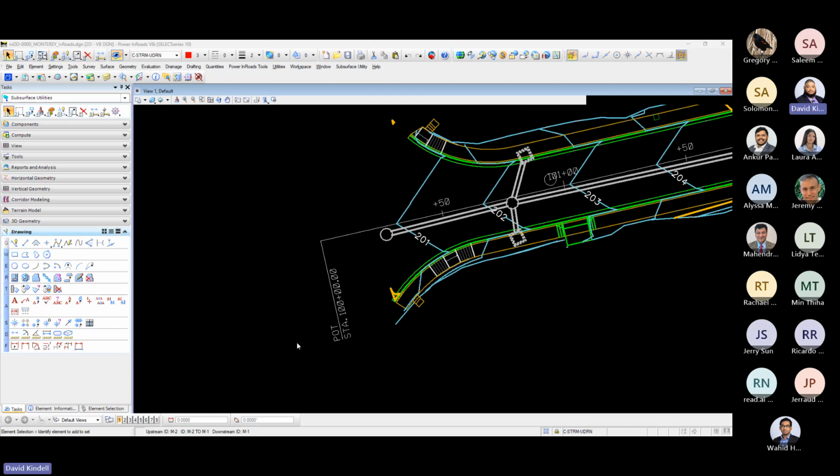So this pipe here, the invert in, as you see, is coming from manhole 2 to manhole 1. So invert in is referring to the upstream pipe that's coming out of manhole 2. So that is in to manhole 1? Correct. Okay, I see now. And the invert out will always refer to the downstream end of the pipe.